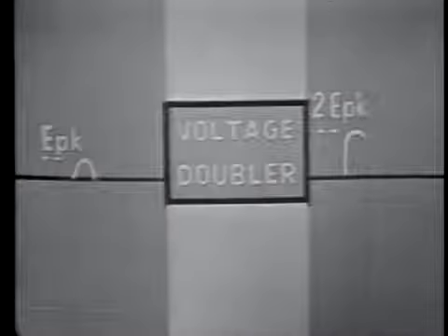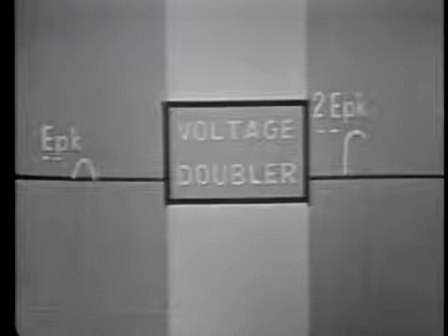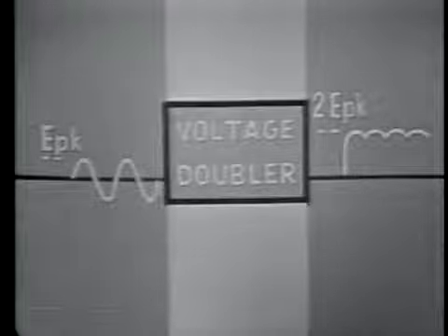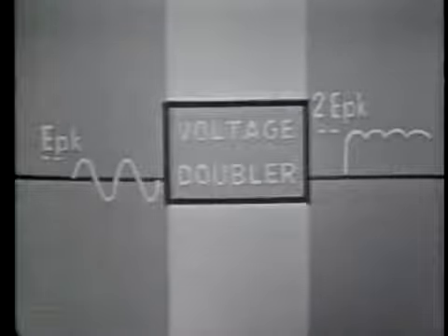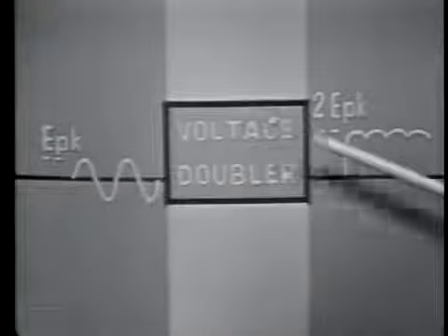One such application of the voltage doubler is in the high voltage section of this oscilloscope. The rectifying action of the voltage doubler is similar to that of other types of rectifier circuits in that it converts an AC voltage into a DC voltage. And it can operate as a full-wave rectifying device, whereby it doubles the input to output frequency.